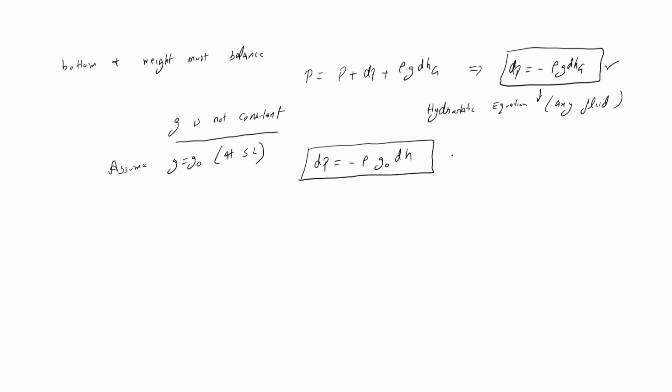Alright, so let me take this as equation number 3. So one thing you must have noticed here, I have mentioned of course G as G naught, but instead of dHg, I mentioned here dH. Alright, the reason is, yes, because this is an equation, so LHS must be equals to RHS. Since we are changing this G to G naught, so there must be a change in H. There must be a change in the altitude. So this altitude we call it as geopotential altitude.